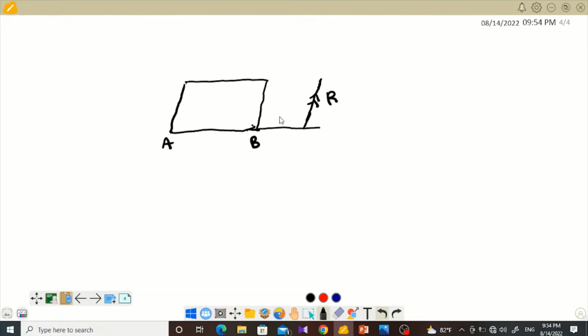So I have to add a couple to this system and move this resultant force to act through the point A. To do this, I am going to add a force in the opposite direction to our resultant force, with the same value.